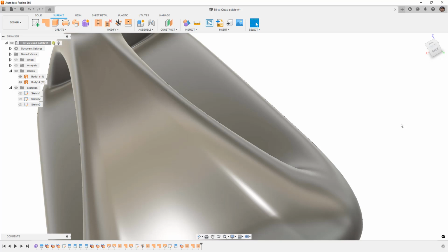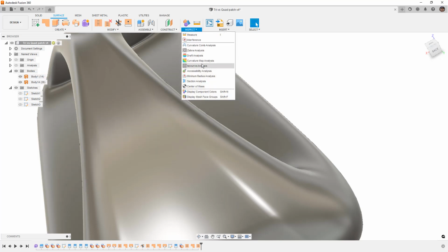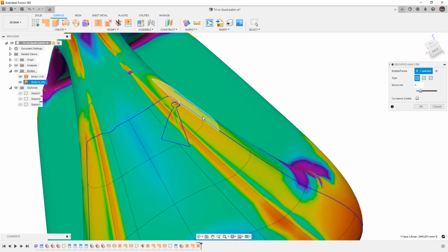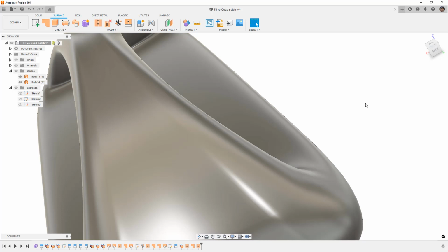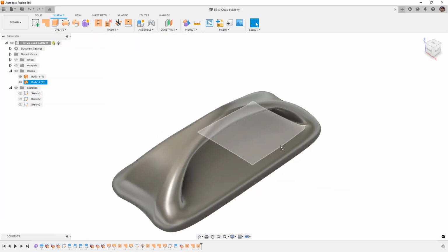If we have our UV curves, which are the curves that are wrapping across the surface, when we take a look at those ISO curves or those UV curves, when we have them in multiple directions, that is going to be problematic for the patch tool. That's where we really want to look at 4-sided openings and using the loft, making sure that our profiles are on those edges with the biggest change in curvature so that we can drive that across that shape. Now, once again, these are not universally true. There will be exceptions to every rule, and it will be based on geometry.